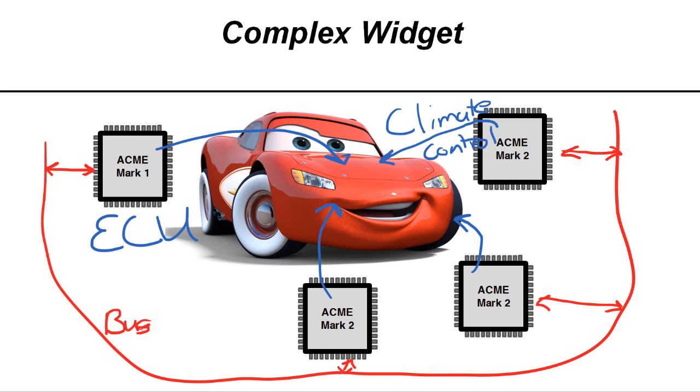For example, in automotive, a very popular bus, because it's very robust, is called CAN bus, Controller Area Network. It's a neat bus made of 2 wires that you can send little packets or messages of data between a bunch of different nodes. And the way a car works is you just have a lot of these microcontrollers distributed throughout the car for all the different functions, and they all talk on one or more, say, CAN bus.